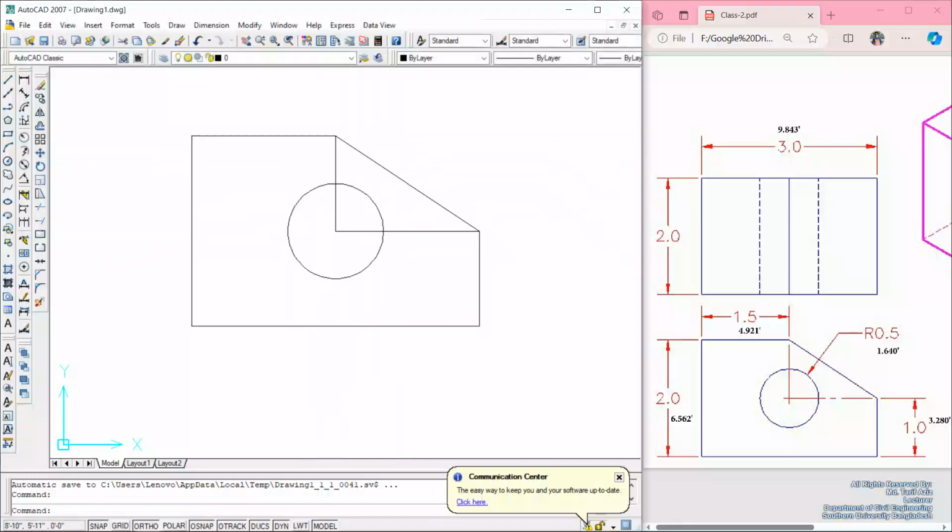So our overall drawing is done, but we want to show the dimensions and we want to show all the lines and dimensions in different colors. So how can we do it? We can work on the layer options here to show different colors and to draw the lines and other things in different colors. So there is only one color right now, but we want several options like this. So just go to the layer properties manager,